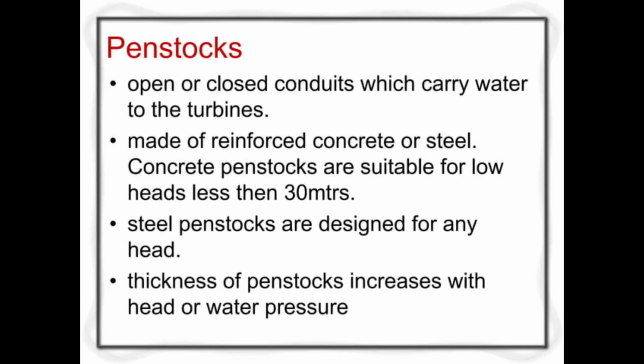Penstocks. Open or closed conduits which carry water to the turbines. Made of reinforced concrete or steel. Concrete penstocks are suitable for low heads less than 30 meters. Steel penstocks are designed for any head, that is, for low head as well as for high heads. Thickness of penstocks increases with head or water pressure.